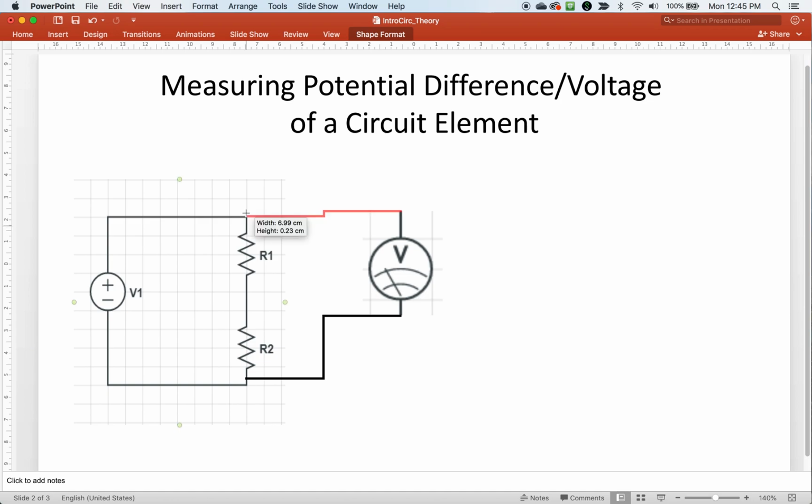And it doesn't matter where I connect them, if I connect them here and here, etc. It's becoming a little messy. It looks like my probes are going across here, but the idea is any measurement from any point along here to any measurement across here, the voltage will always be the same. It'll equal the voltage of the source, but it'll also equal the total voltage drop across both resistors. And so you keep playing that game, you should see this voltage plus this voltage should equal the total source voltage.